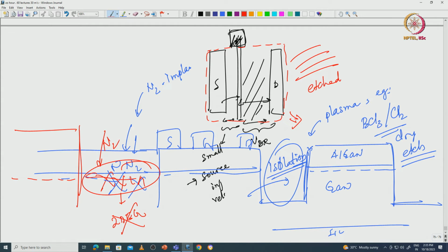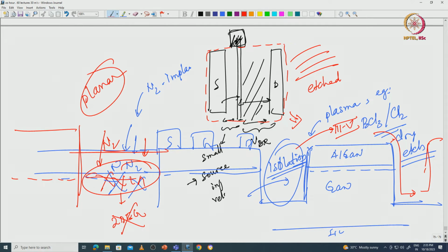So, that is how people do it in industry in many cases, because then it makes it a planar process. This is a non-planar process. You see there is a step here, then a step again comes up. This is also done in industry, in III-V industry typically, but this planar process, where you have implant done, is typically in CMOS fabs. So, if you are going to use a CMOS process, a CMOS fab line or foundry line, people might want to use this kind of a planar process as opposed to a physical etching process, but that's separate, besides the point. But this is your isolated pad.